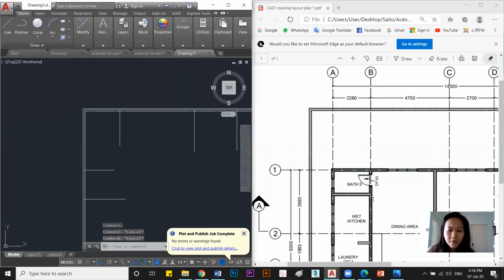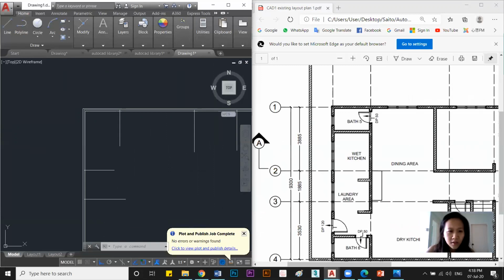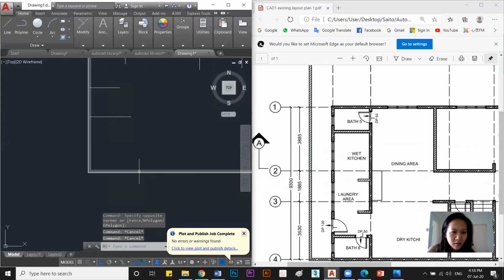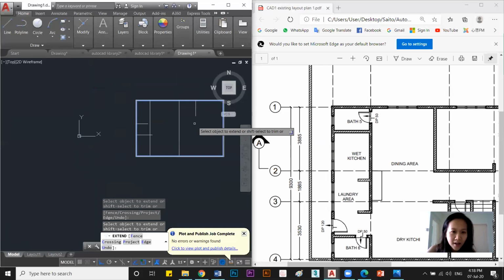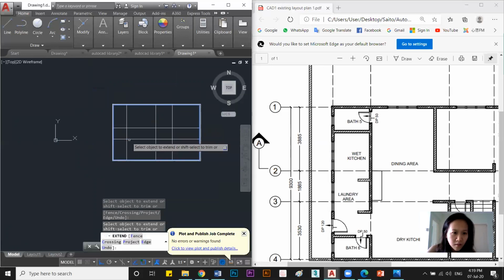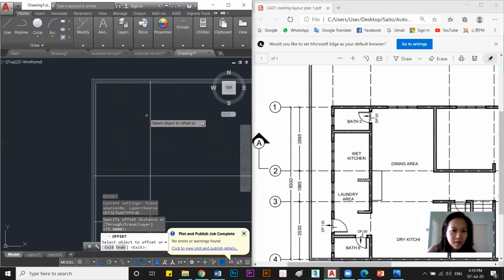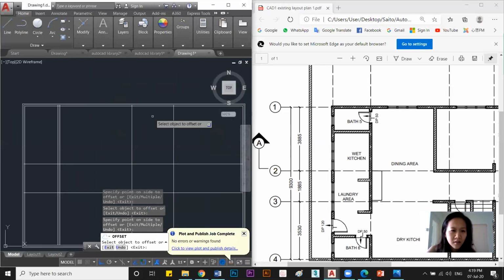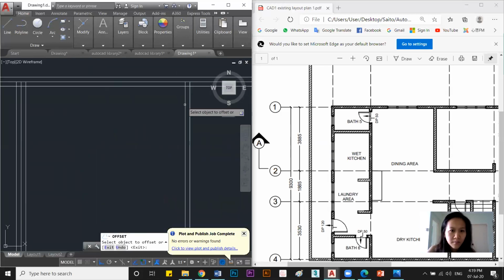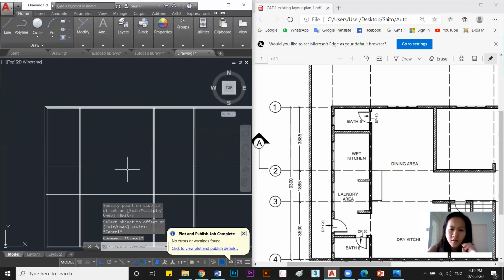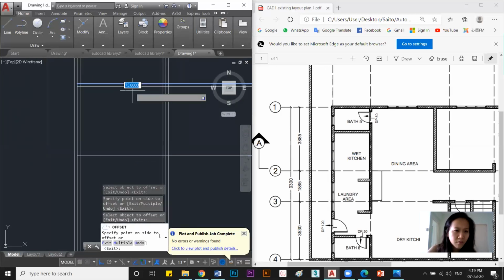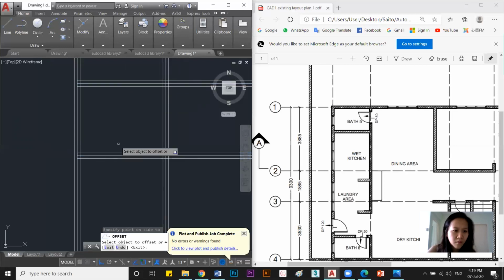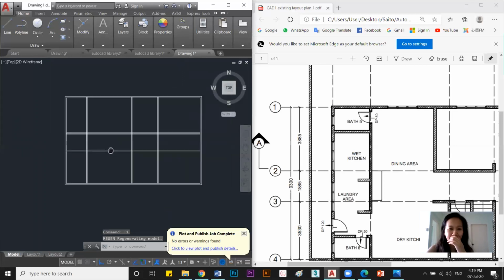All right, so now the buff. We draw this first. Extend this. How to extend? Extend the line first. Then you offset 75, 75 to the left, 75 to the right. Left and right. Here as well, offset 75 up and down. Okay, refresh.